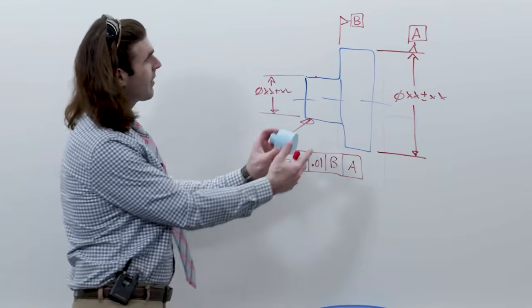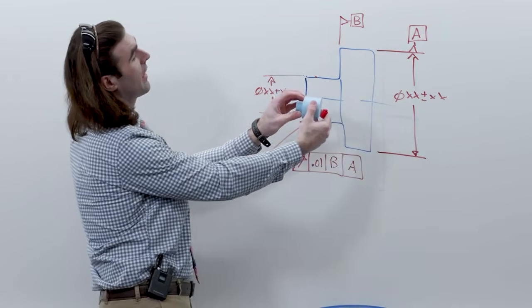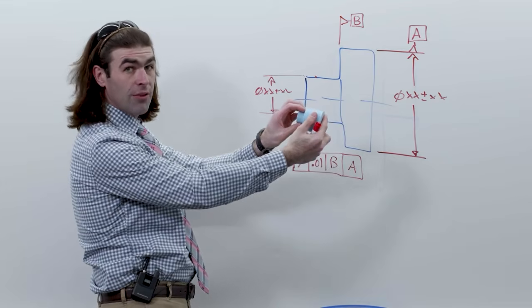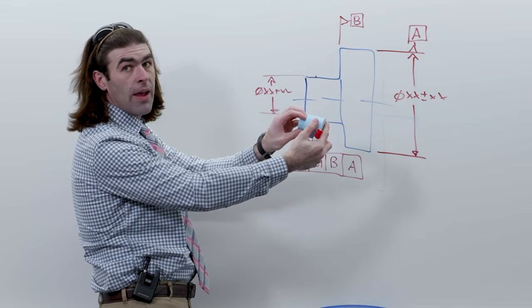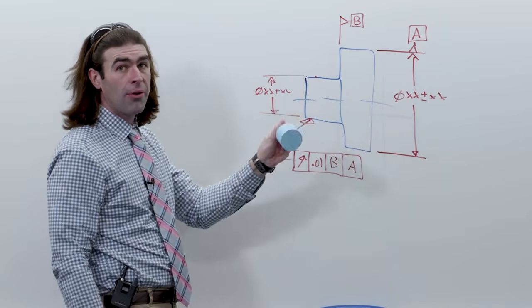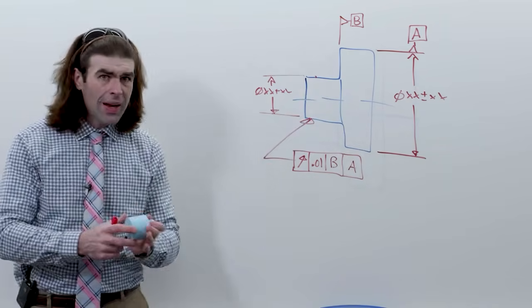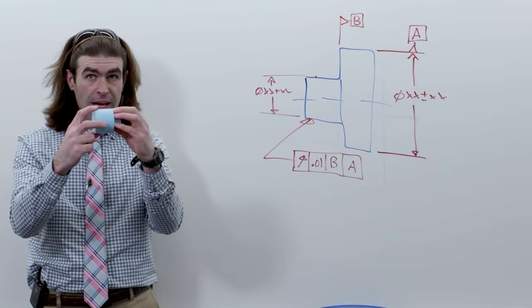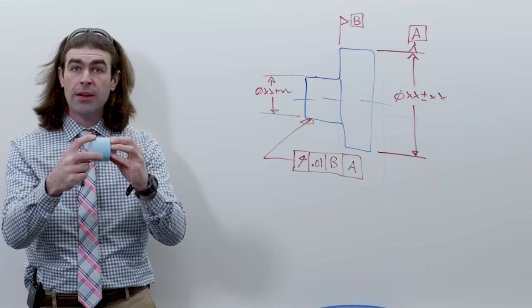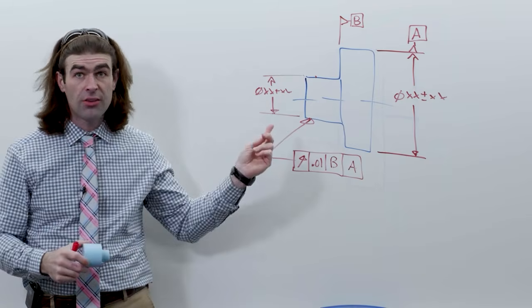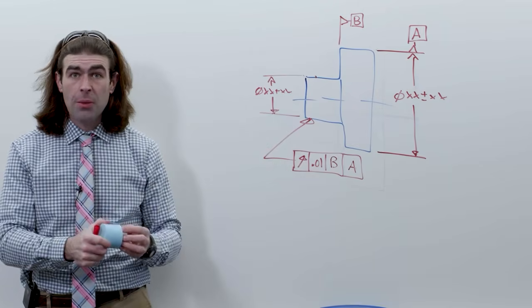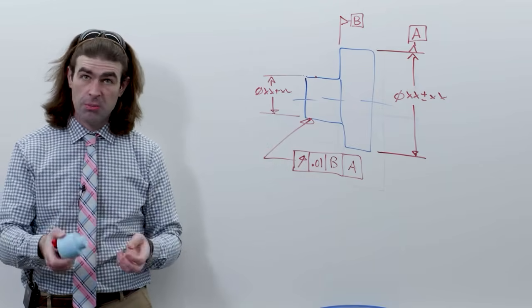So in this case, we make full contact with datum B, say against the nose of our chuck or collet or V-block, and then clamp down on A, and then we could spin the part around. So you can have a situation where you make full contact with B, and then A only grabs on one point. And that would be okay in this situation. You're saying B is more important than A. B would be the mating surface at assembly.